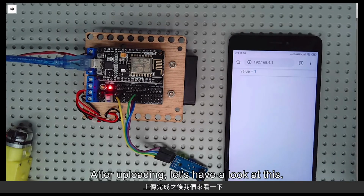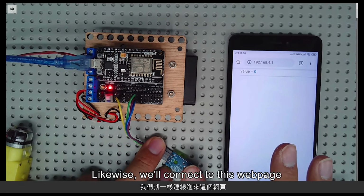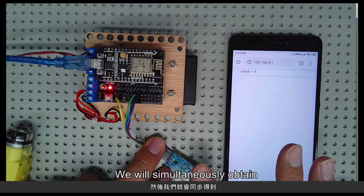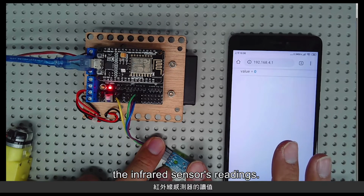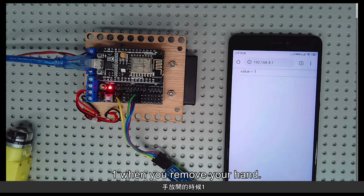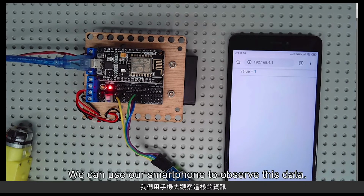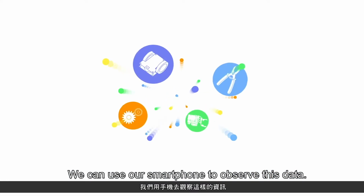After uploading, let's have a look at this. Likewise, we'll connect to this web page and then approach our finger. We will simultaneously obtain the infrared sensor's readings. It's 0 with an obstacle present and 1 when you remove your hand. This is the method. We use this transmission method to transmit the sensor signals. We can use our smartphone to observe this data.